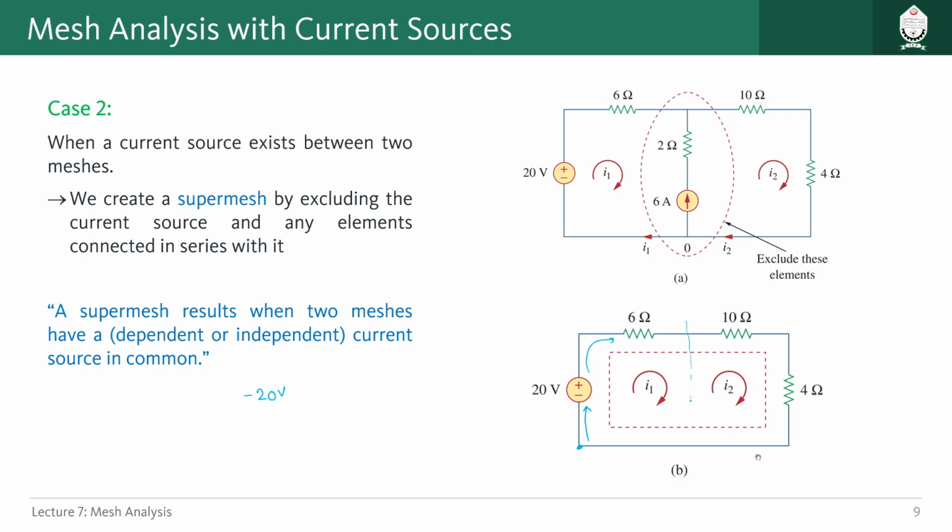If you think about the previous circuit here, all the currents for this mesh were contributed by I1. So 6 ohm will only get currents from I1 mesh current. As a result, I1 current is flowing through 6 ohm, and we can represent this voltage drop across 6 ohm as 6 I1, right?